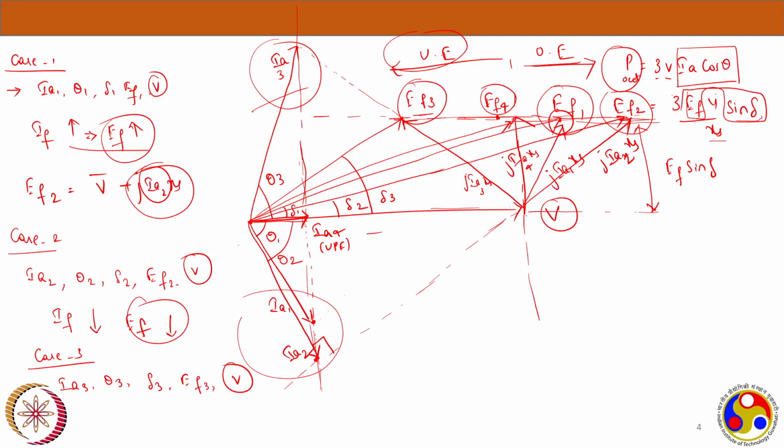Now you can also see the lengths of the IA armature current magnitudes. Let's say I have started from under excited. Here is my IA3. I'm slowly increasing my excitation, so IA will have this locus. Maybe here, then here, so it will slowly reach this point, IF.